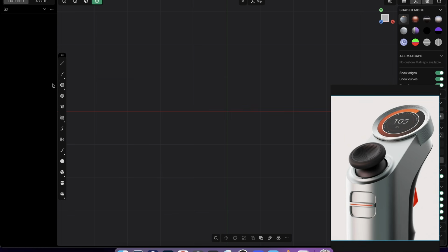And we want to start with a simple circle, because you see this main circle, so ignore this cylinder here and this joystick, but we have here this cylinder shape. And that consists of two circles. So let's create a circle, key on the left, center circle, snap to the middle. And now when you drag out, just make sure that you snap either to the y-axis or to the x-axis, and something like that.